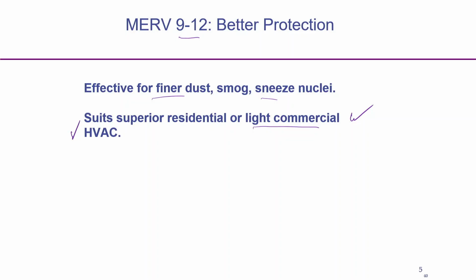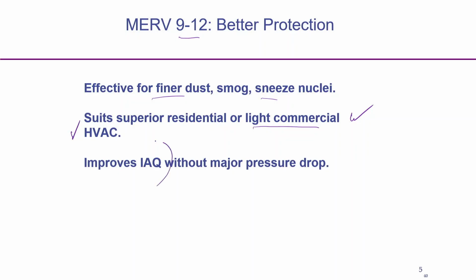Even from the vehicle exhaust we get different types of particles. For those applications we need MERV rating 9 to 12. It improves the internal air quality better than earlier. Pressure drop is there, but it is not too high.